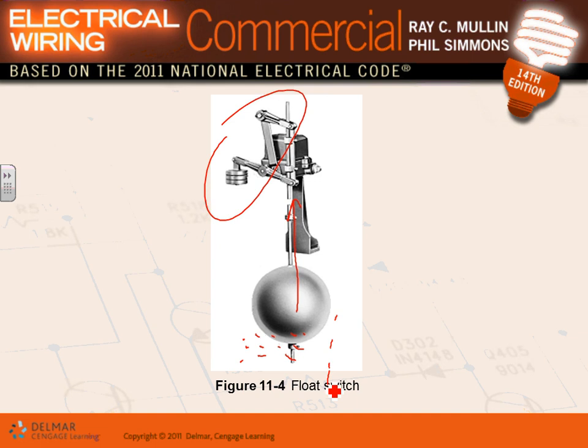So what they do is they have a range, guys, otherwise it would be turned on and off, on and off. So there is a range where it operates. Here's my on, here's my off. When it reaches this point it's off; when it reaches this point it's on. Any comments, any questions? So when it starts, it keeps pumping until it empties to this point and stops. Then it keeps waiting until it fills up to this point, and it turns on again. Can you guys understand? Otherwise, it will be on and off all the time, so you have to have a range when they set them up.